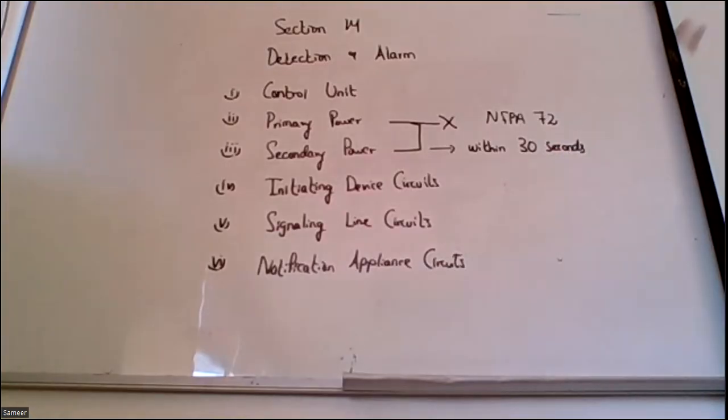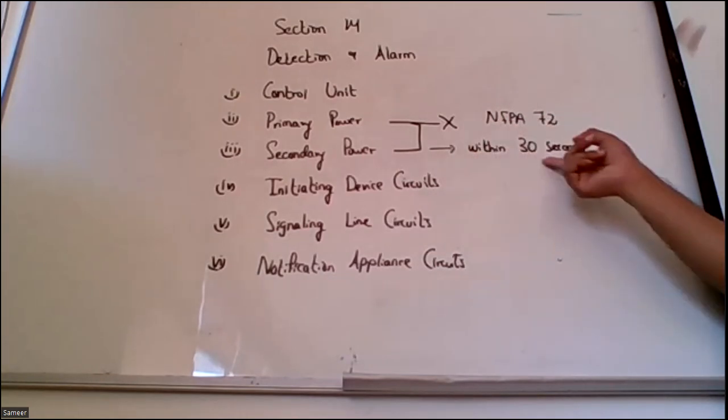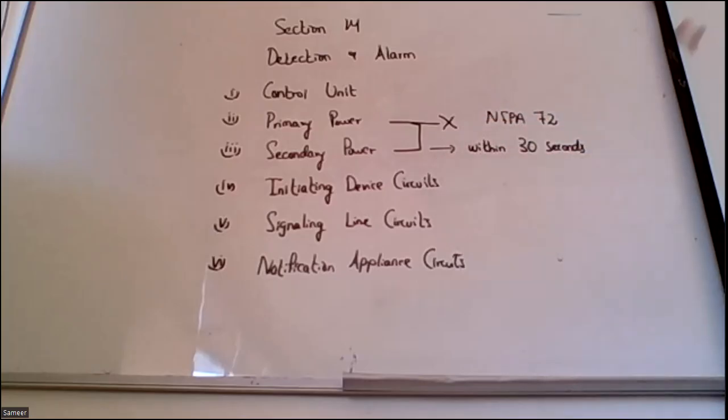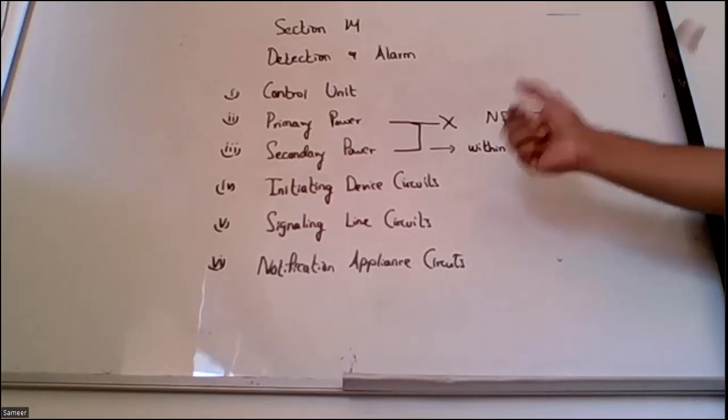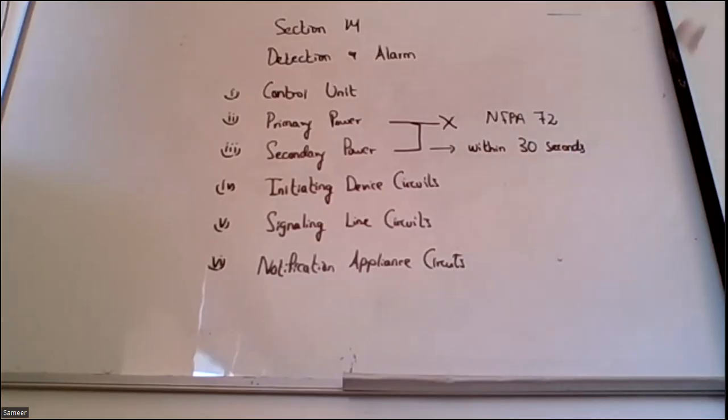When this question comes in the examination, in the start I never used to give any priority to this type of question. But when I added it to my sample questions, I realized that most people always go for the least time. If I write 30 milliseconds, they will go for it because everyone is assuming batteries. NFPA 72 says 30 seconds because it keeps the generator in mind as a secondary power. So whenever your primary power fails, the secondary power should be taken within 30 seconds.